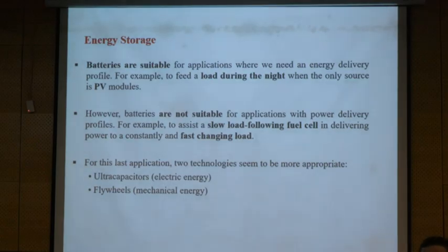But nowadays they say that we use predictive control. Predictive control says that I choose the switching based on the optimal operating condition to minimize the switching losses. Later we will see this one. So control of the converter can also increase the efficiency.